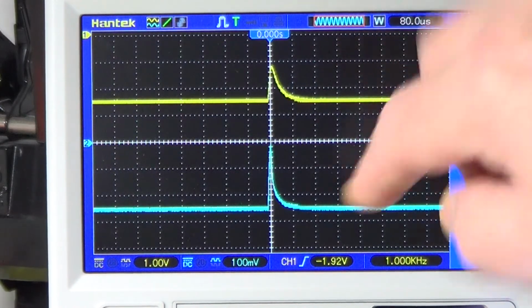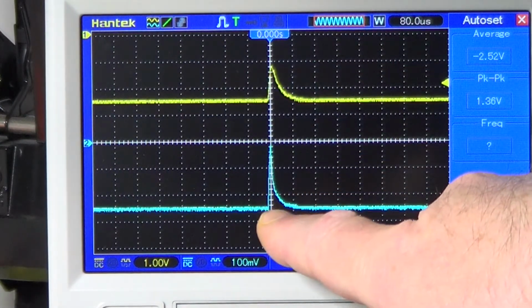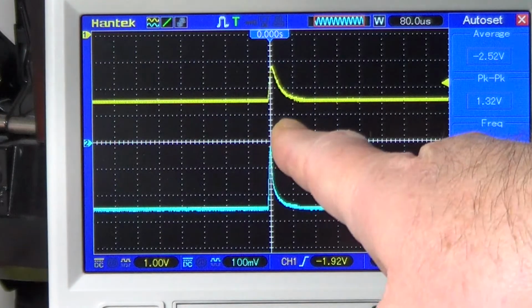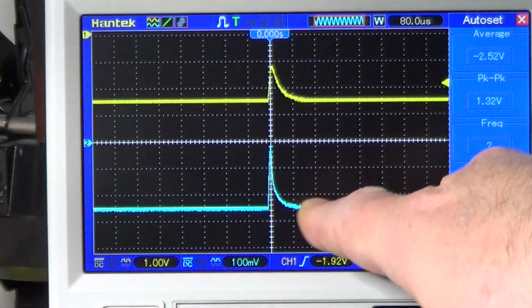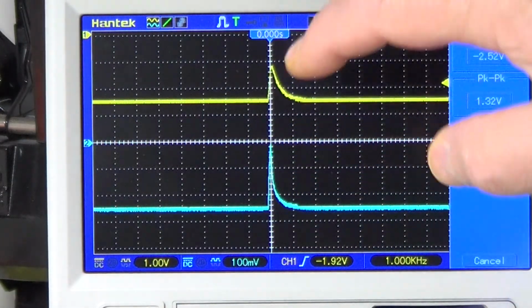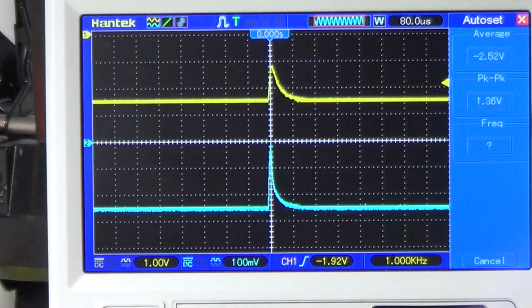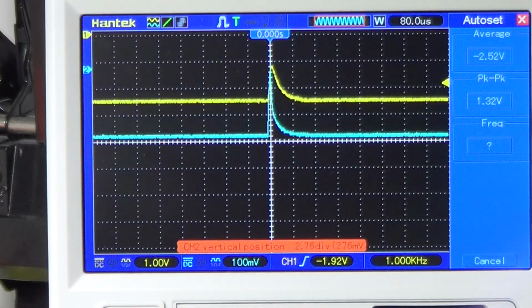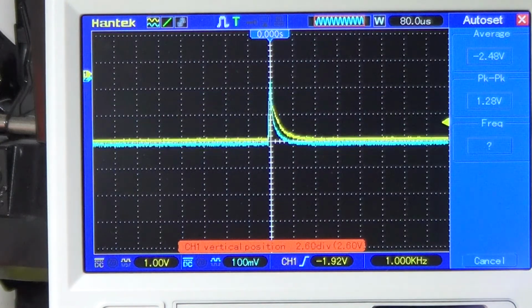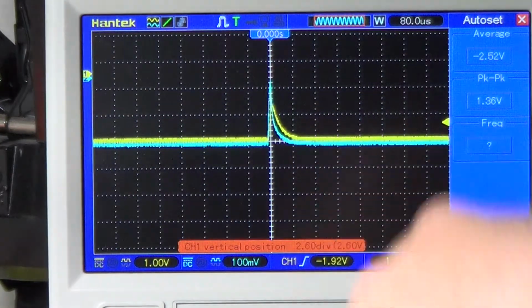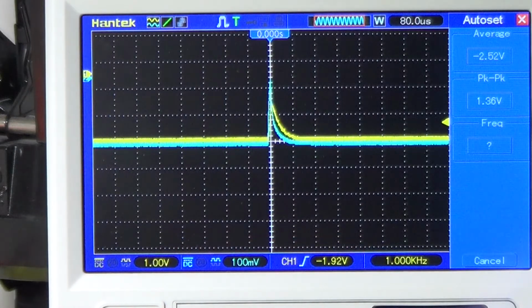You can see how this differs. A very brisk rise and then a relatively slow going down, while here the going up is less brisk and the descending shape even less so. Let's compare them on top of each other. So you can see clearly that the second order filter takes a longer time to extinguish the response to the impulse. And that's all for the passive second order RC filters.